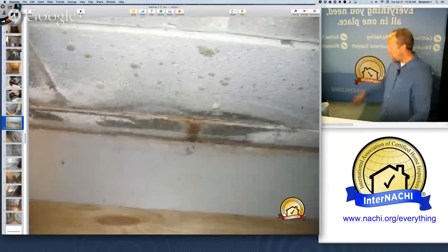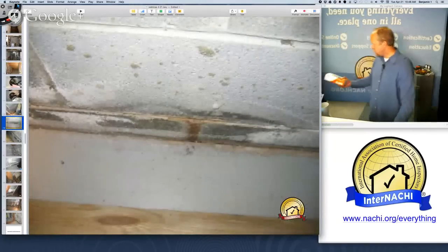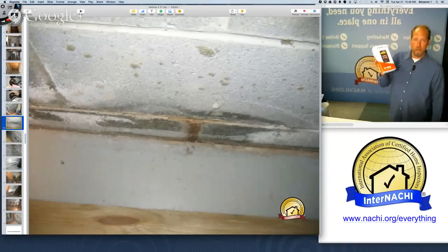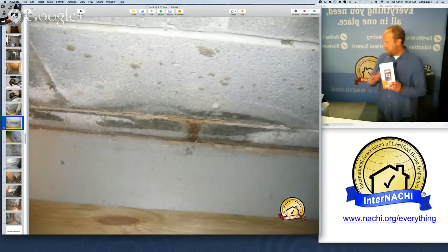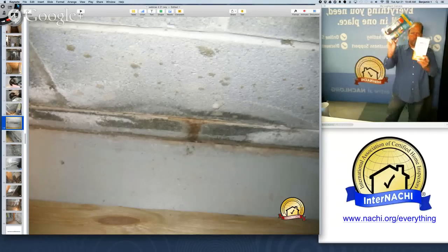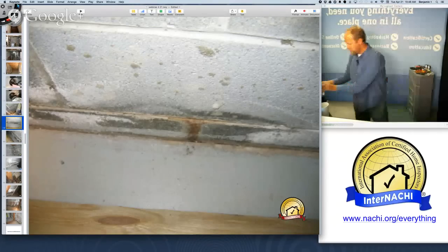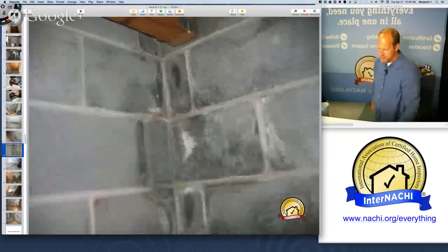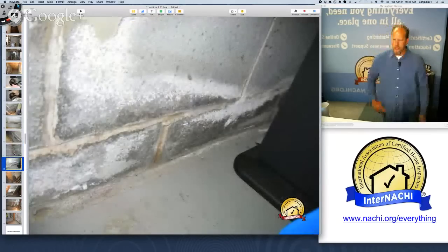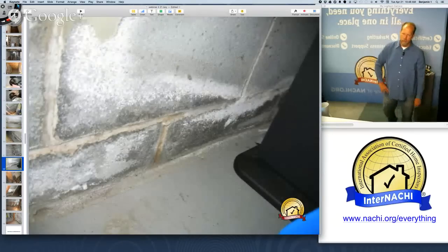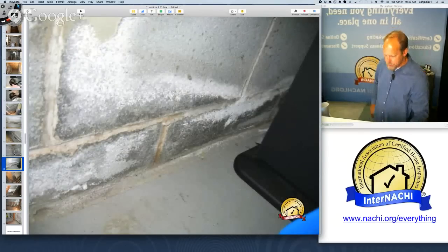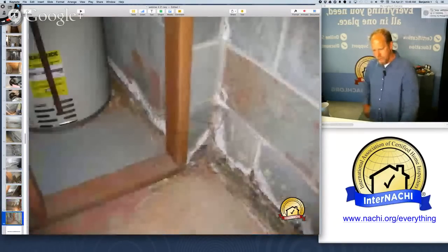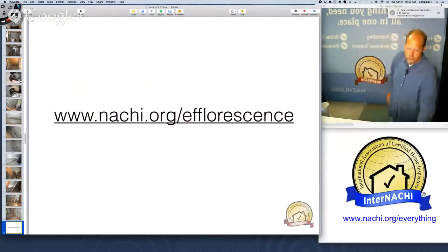A great home inspector is essentially a really good moisture inspector. We have a certified moisture inspector certification program, a training program, but we also have on InspectorOutlet all of these moisture meters and tools to help you identify moisture. And yeah, efflorescence indications just about everywhere there's exposed foundation wall. I'm looking at moisture, indications of water penetration, moisture intrusion, efflorescence, and probably a lot of humidity coming into the house as well, into the basement.